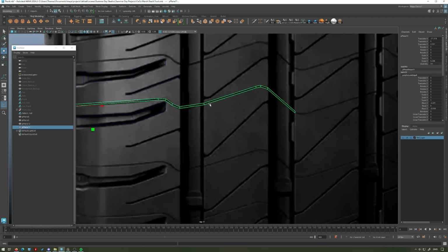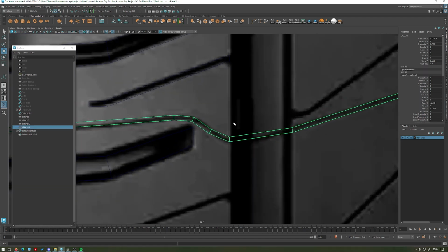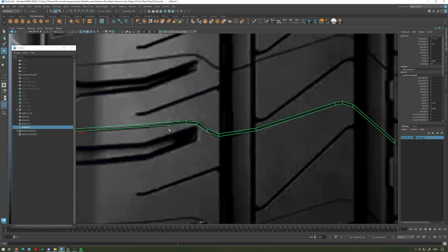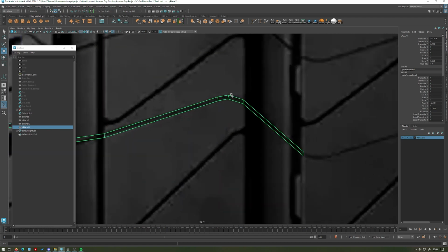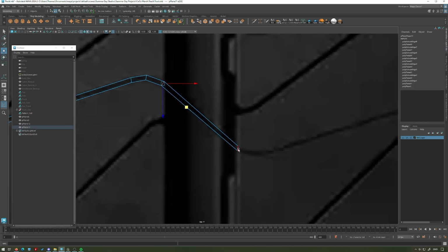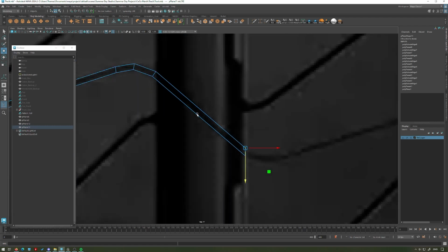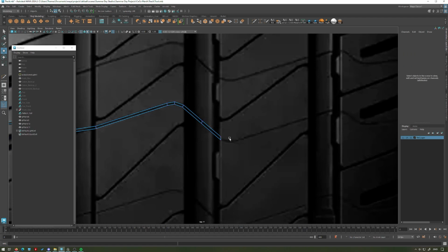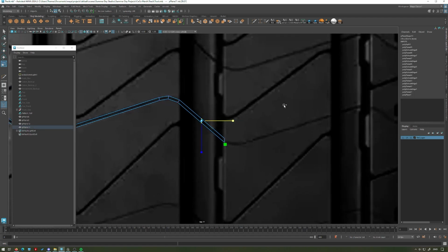Okay, so this is how much I've made, and I'm paying attention trying not to make this too complicated for the time being, topology-wise, because we don't want this to be too dense. So for these curved parts, I'm only adding a single extra division in the middle, and then having 2, one at the start, one at the end. And right here is the halfway point, so I'm just going to add a cut, literally running straight down the middle, and I want this to be going flat.